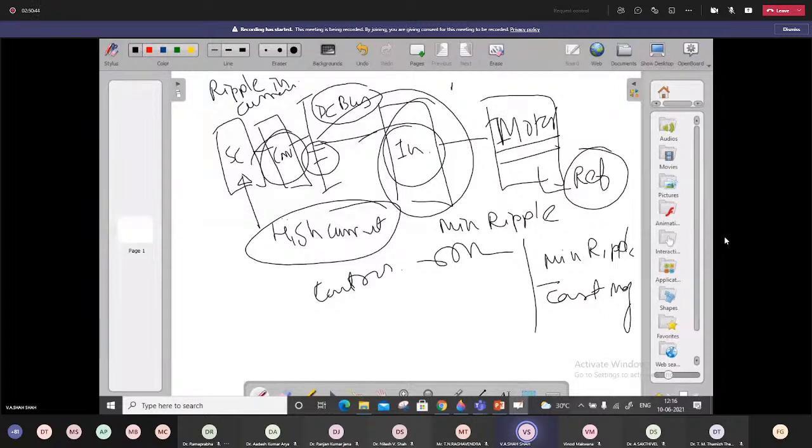Ultimately, we are controlling the power from the source. So the control of the source is in such a way that finally the current drawn by the motor must have the minimum ripple, or you can interpret it in terms of harmonics. So you have to adopt an appropriate control strategy for the motor as well as for the inverter.